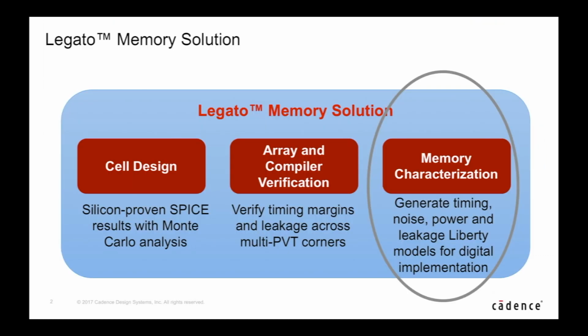solution. The Legato memory solution is a comprehensive new product that covers several aspects and possibly all aspects of memory design, verification, and characterization. Specifically today I'm going to talk to you about the memory characterization portion and dive a little bit into the details of how we generate the digital models for timing, noise, and power and leakage that are used in the digital flow, and also briefly talk about some of the verification, data manipulation, and the compiler integration that we provide into the new solution.